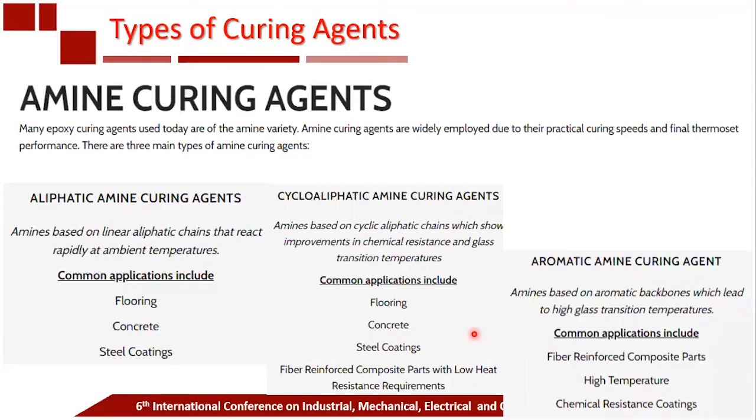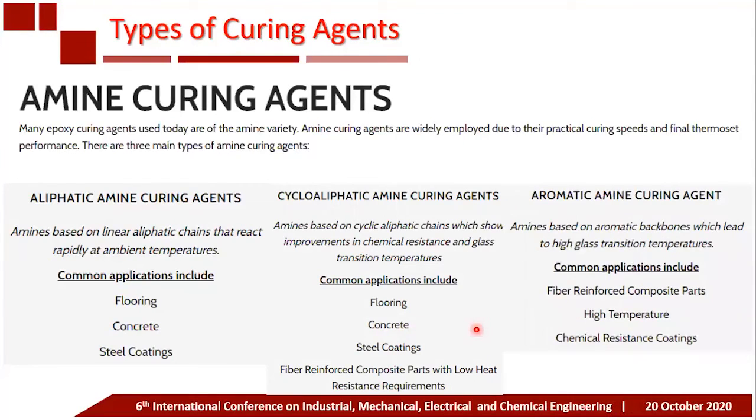And the last of these amine curing agents is aromatic amine curing agents. These are amines based on aromatic rings, which lead to high glass transition temperature. These curing agents are blended with epoxy for fiber reinforced composite parts at high temperatures and for chemical resistant coatings.